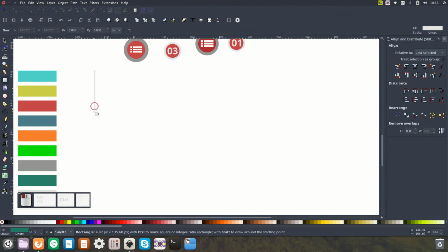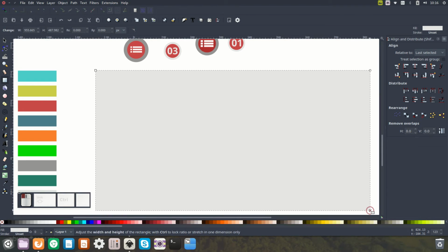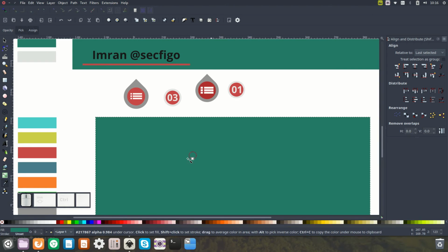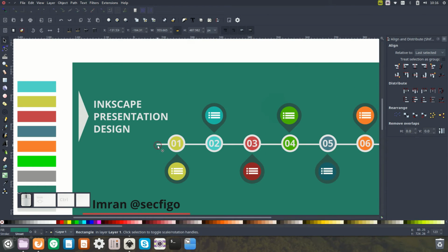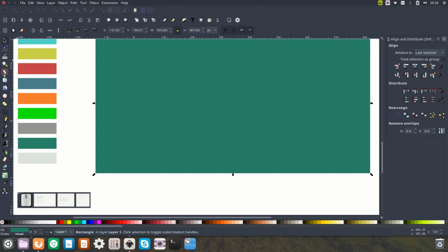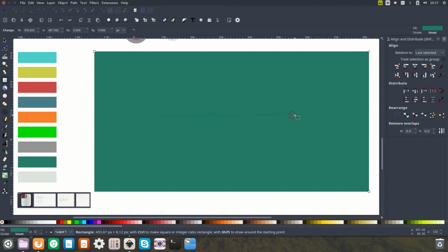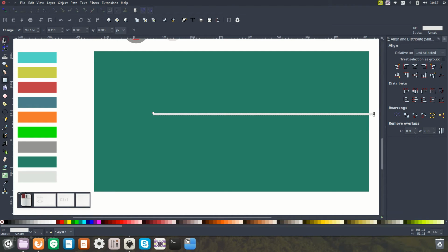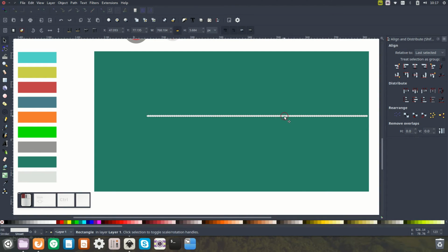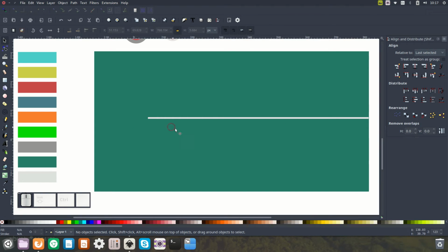I'm going to select the rectangle and square tool. Now I'm roughly drawing the circle, whatever feels right. Okay, with this selected, go to the color picker and click on this. This is what the color is here, so you can also click on here and we'll get the color. That's done. That's nice. Then we have a line, so we can create this line by going to the square tool again. I'm drawing a rectangle, but it's not visible because the color of this rectangle is the same. So let's change the color to this one here. This looks good. Probably reduce the width a bit. Okay, that looks much better. So now we have a line.